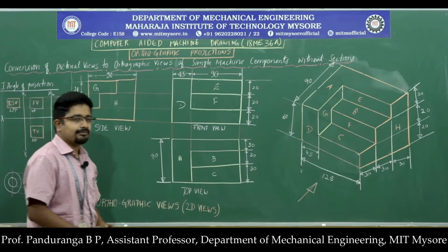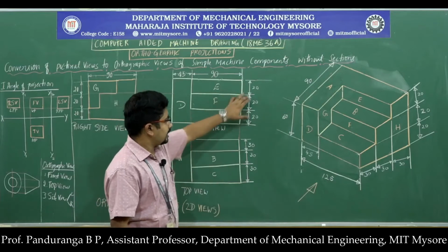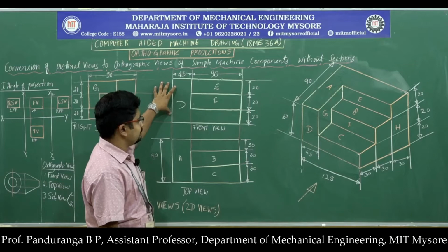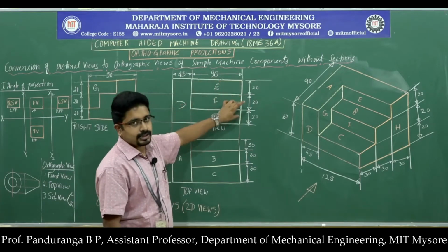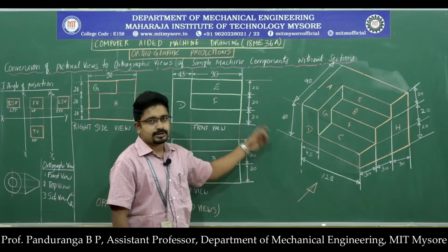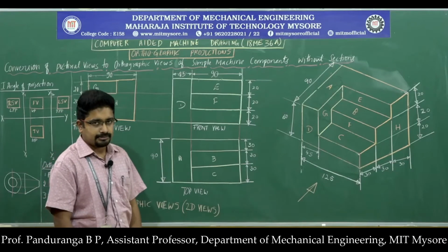So these two methods can be used in ISO standards. Okay. Now I will write all the dimensions. Again here if you see, the total height is 60 mm. So this is 20 and this is 20. So the third portion will also be 20. So this is a redundant dimension. You can write or you can omit the writing of that dimension.